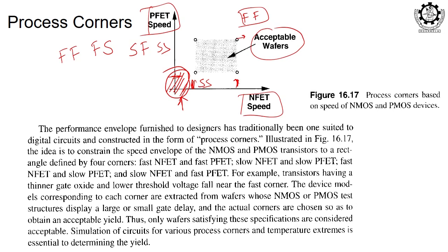If you want to check your performance, generally when you do the simulation in your lab, you do simulation at only one corner. You are not changing the technology, your process is at typical. So, whatever the values of VTH, whatever the values of mu n, they will take the typical values. But if you go for fabrication, you do not know what will be your mobility, what is your VTH, you do not know.